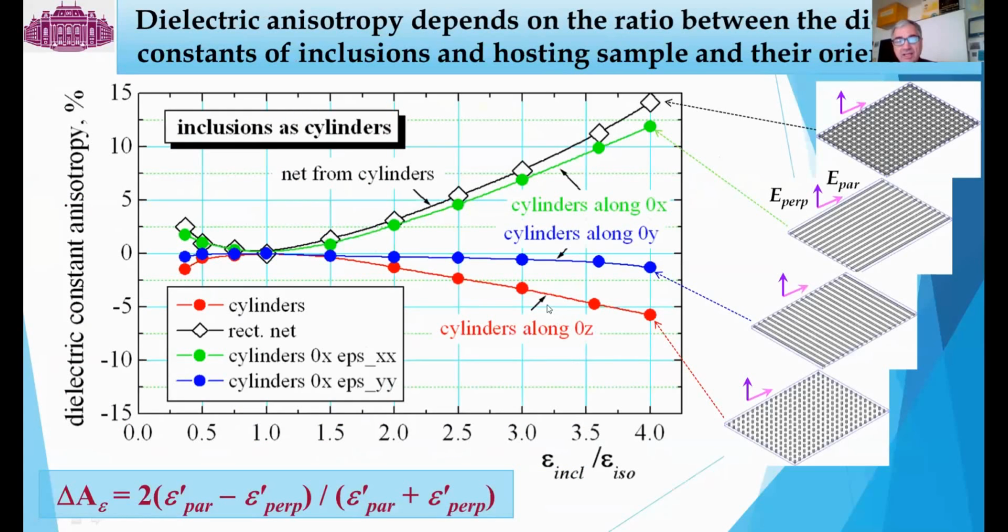We tested this method, for example, for knitted and woven textile fabrics, and for some metamaterials, and found out that if the electric field lies along some fiber, a cylindrical fiber for example, the dielectric constant increases in comparison with the dielectric constant perpendicular to the fiber. This is important and gives us an idea how to minimize dielectric anisotropy of materials.